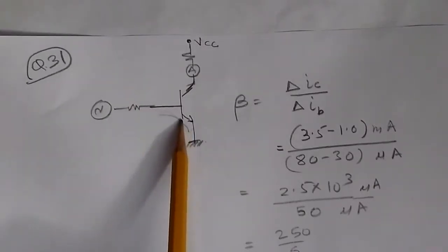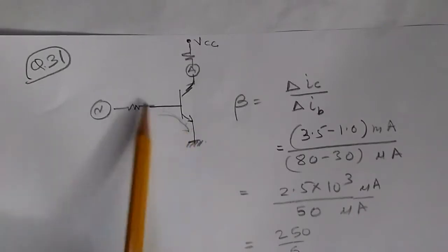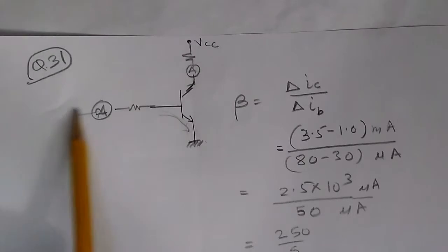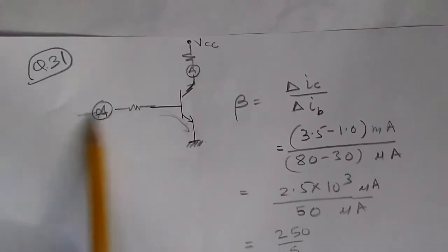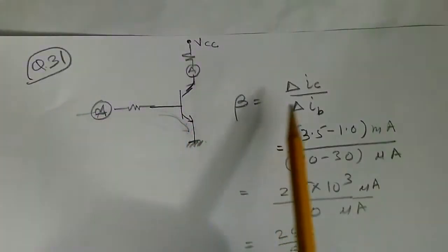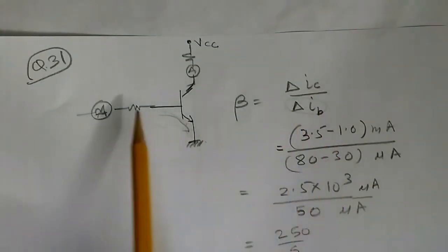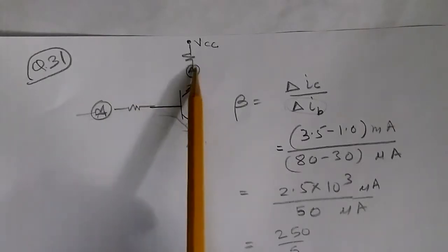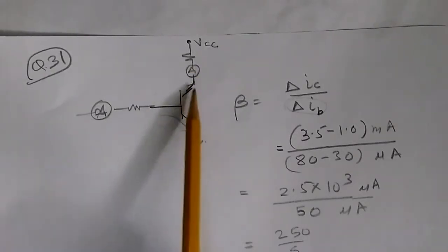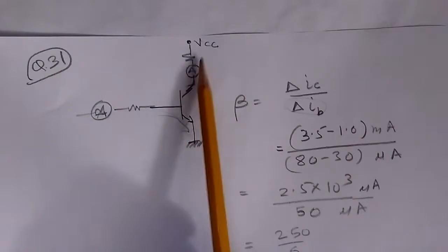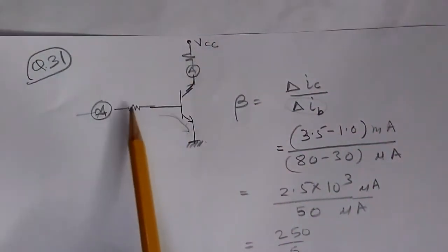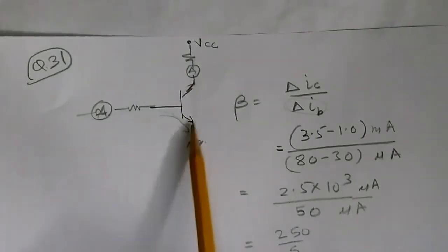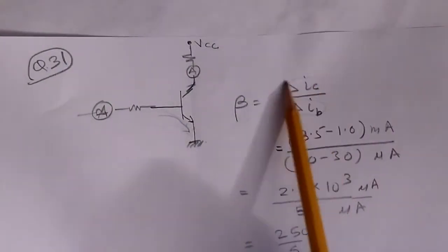When you change the voltage, there will be some current flow from the base to the emitter, and we can measure this current if we apply an ammeter. We call the change in the current delta IB. If you slightly increase this current, the channel between the collector and the emitter gets wide, and there's a huge inrush current, a much better amplification, a much larger change in the collector to emitter current, and we call it delta IC.